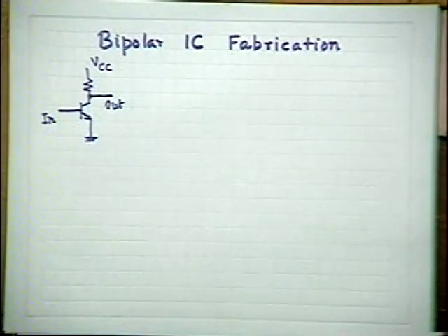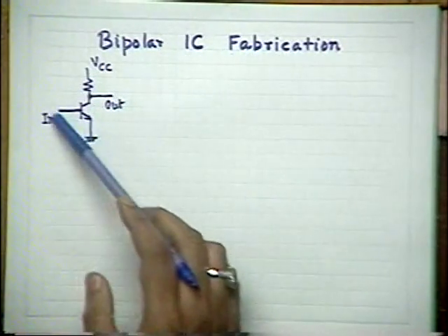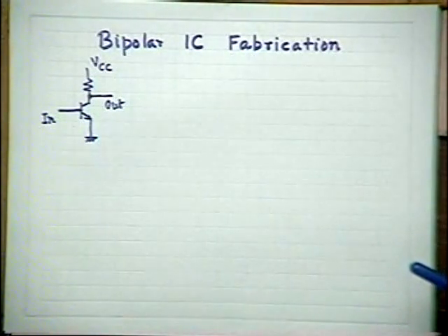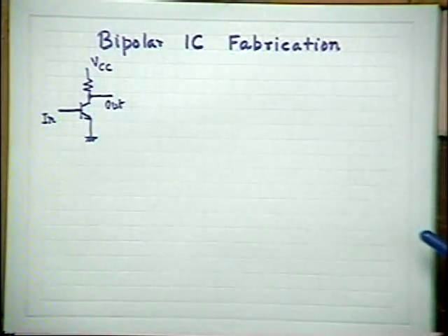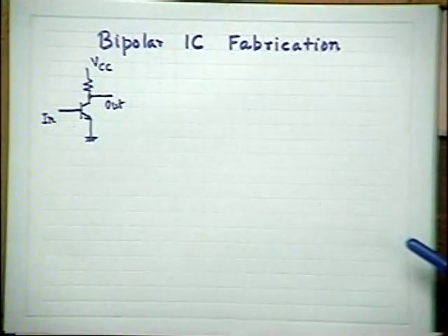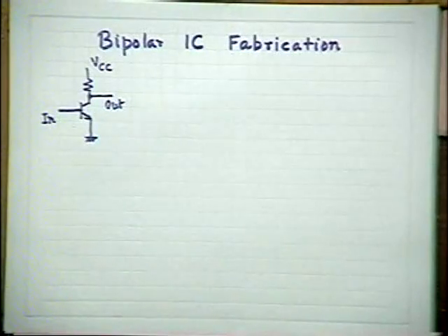Normally, we use the transistor in two modes for digital operation. One is cutoff, when the emitter base is either zero biased or reverse biased, and the other is saturation, where emitter base is quite strongly forward biased, which leads to strong saturation of the transistor.